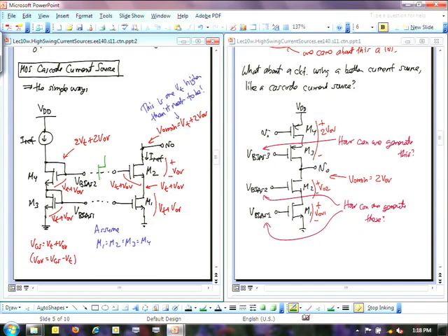So you transfer this IREF current to here. That becomes IREF. And then up here, you're going up, and now you have a couple PMOS devices that are diode connected the same way. So I have diode connected PMOS devices, and these then become my V bias generators.